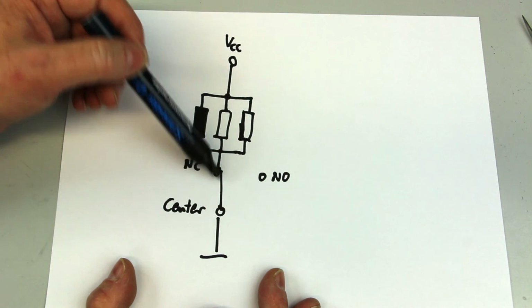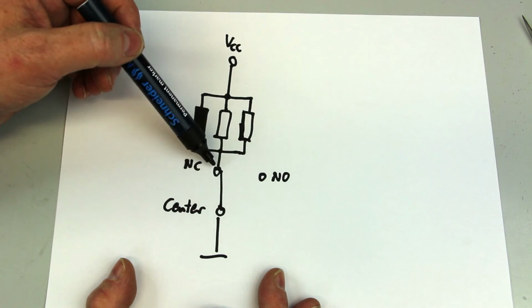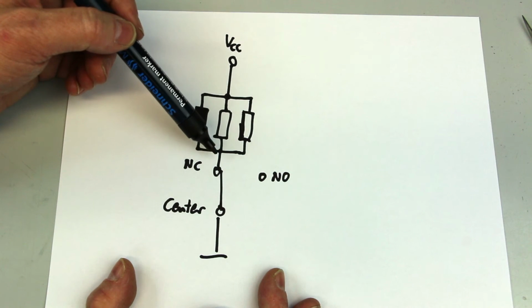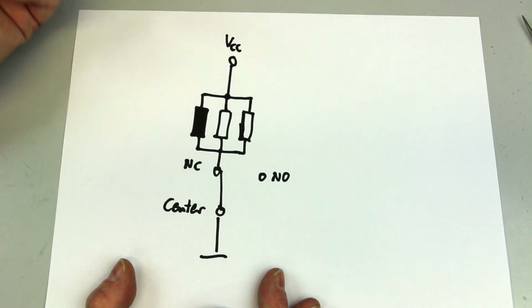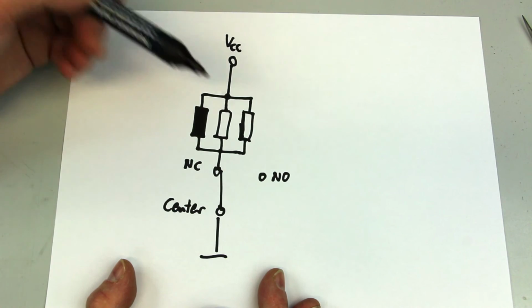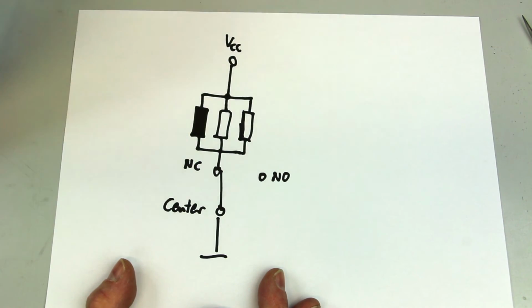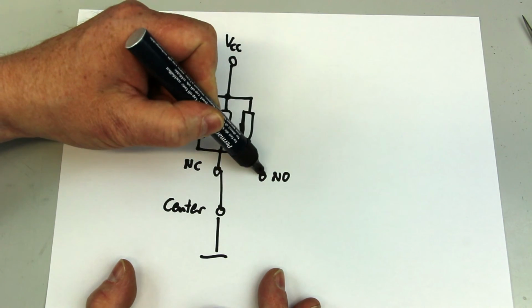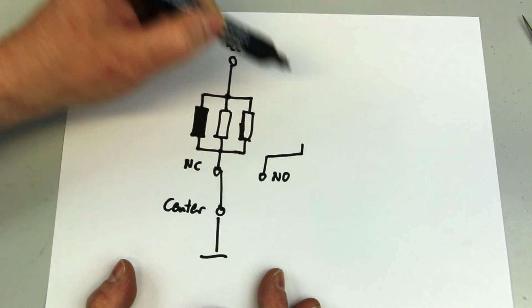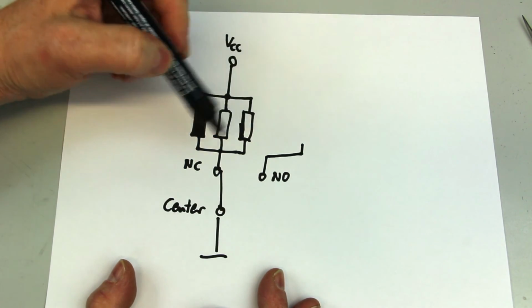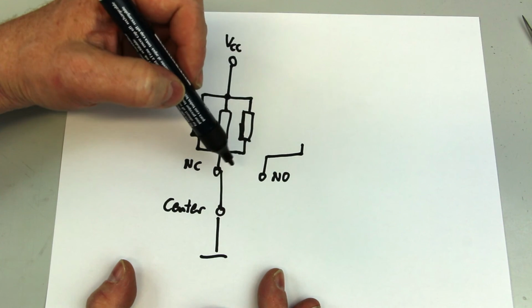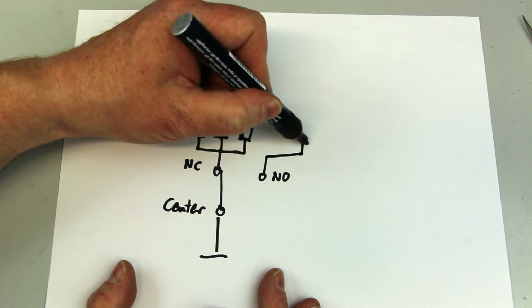We even only need one of the contacts. On the other contact we can still switch one or more other also paralleled loads, but remember the limitation of the total current. And we could still do another trick, this time shown for the normally open contact.